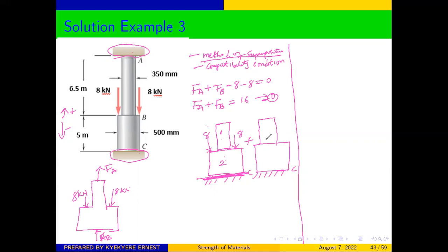And in this case, in the second case, you are going to assume that there is no external force being applied. So we only have the rigid support at A, and we have already stated that the reaction at A, we will call it FA. Good. So the first instance is helping us to determine the deformation associated with external forces.